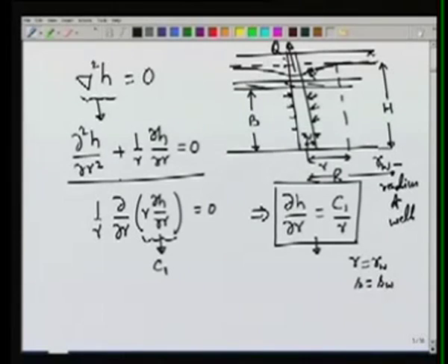So we can show it here. SW is the drawdown in the well. One condition may be that R equal to RW, S equal to SW, but typically the drawdown in the well is affected by some losses in the well. The flow is also not laminar, it's turbulent.